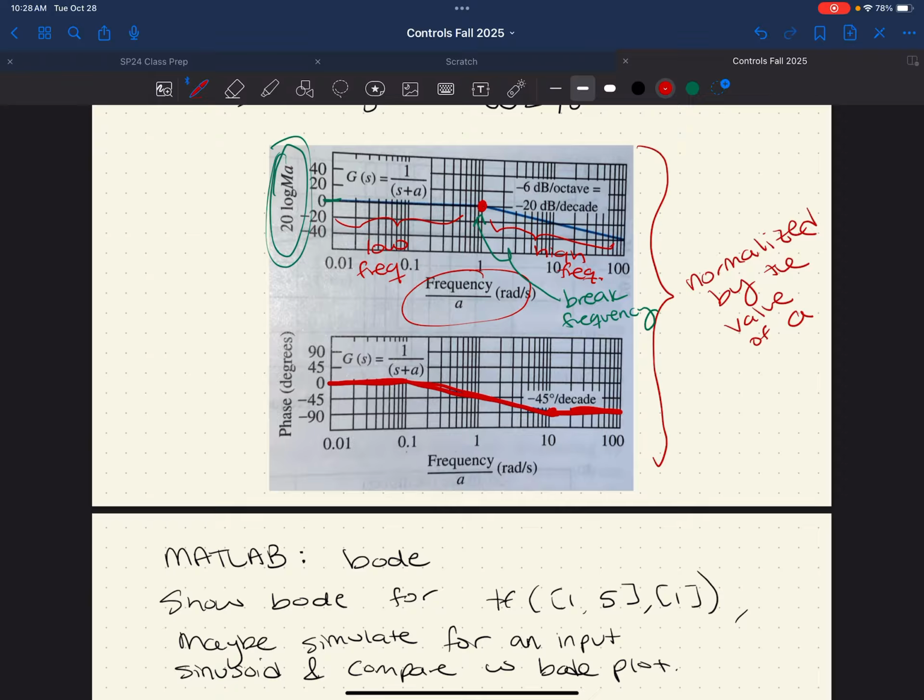Yeah, so I start out by roughly 20, and when I'm up here at the top, and I'm definitely nowhere near that tall, I'm up at 40. So I go up by 20 decibels within this decade, so my slope is 20. So I would say we did a pretty good job of estimating our Bode plot here. We could do the same for the pole.